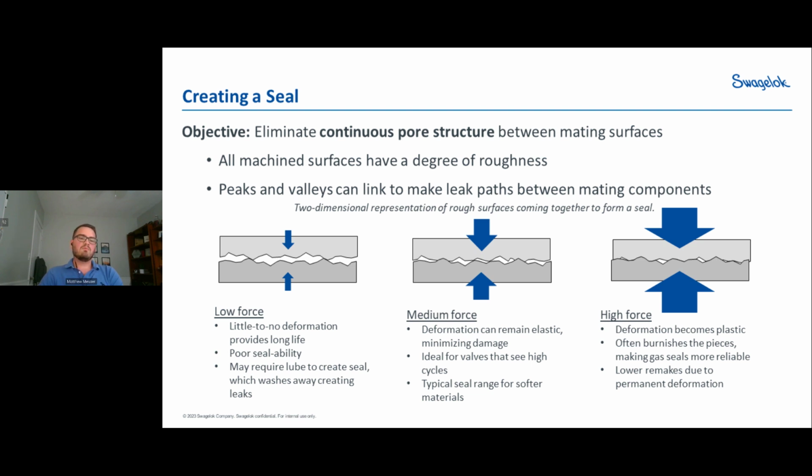When we talk about a higher force, the deformation is going to be plastic, which is more similar to what you'll see in a fitting material, where you're actually going to be burnishing the pieces together and you're going to create a more reliable seal. This means that you'll most likely get fewer remakes due to the permanent deformation, because you're only going to get that elastic degree back with the spring back that the material has.